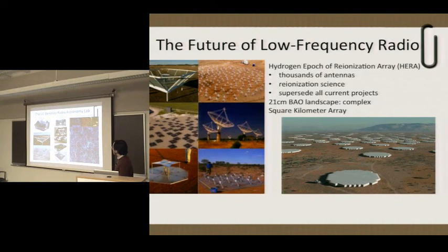And so, I would say we're currently exploring the idea of a hybrid approach where maybe each element could be of a similar design, and maybe without using such a large tile, you could pack a couple of them close together. But there's also some question of, do you need to do that? Can you just throw a lot of digital signal processing at the problem? And I think that's actually a fairly fruitful approach. And so when you get to the idea of building 1,000 antenna or several thousand antenna elements, you need to think about the elegance and simplicity of the system. How do you maintain that many? And it may just be that.